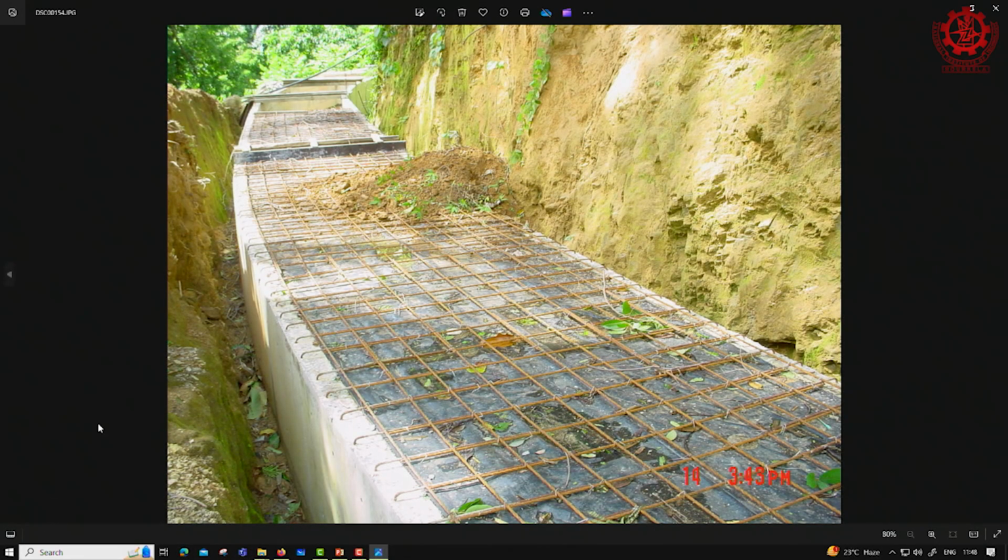Sometimes we box it, we call it boxing, completely covering it, because this soil is liable to fall into the canal. Then your desilting arrangement is going to be difficult. A lot of silt and soil comes in, therefore we want to avoid that. We will completely cover those sections.